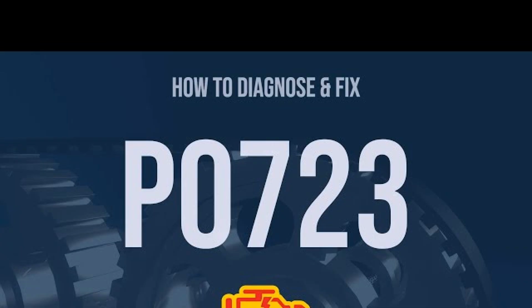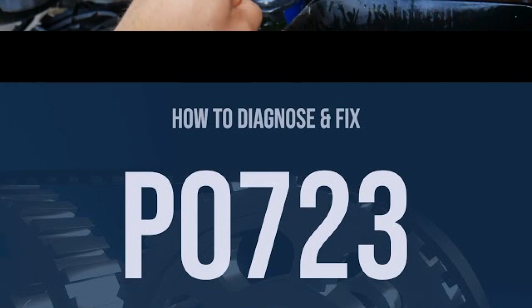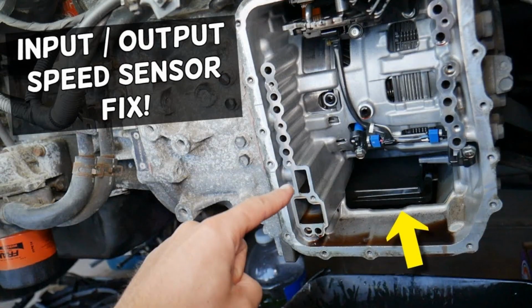Check for an earth fault in the wiring sections by moving the positive or negative conductor to a good earth connection. If there is resistance, there may be a short circuit to earth. The wiring harness should be checked for damage to the wiring harness or areas that could be grabbed by contact with the car chassis. Faulty wiring can often be the cause of error P0723.